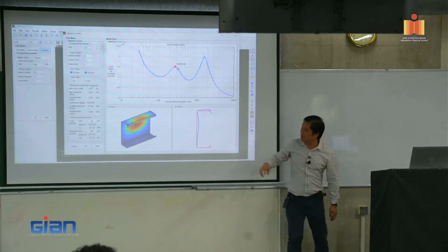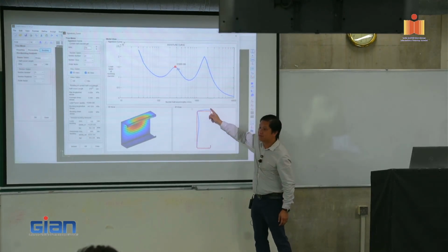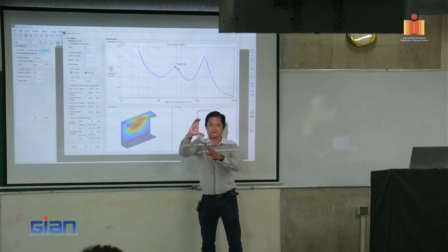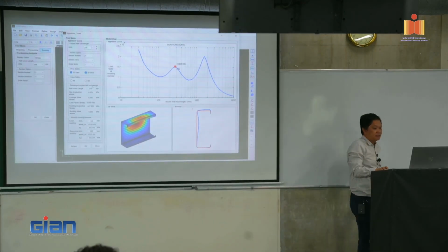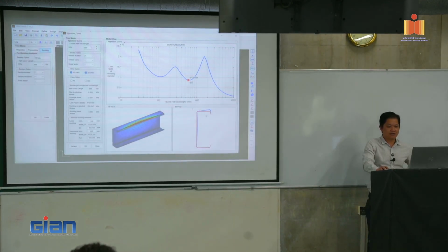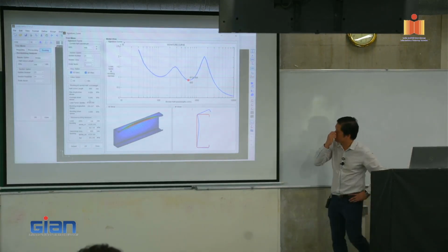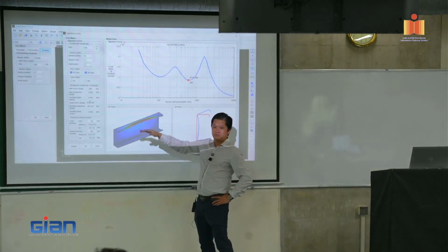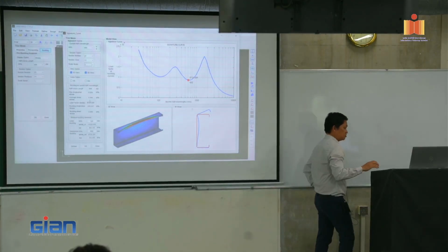And you can see slightly that one moving up in the middle. So it starts to open. So that's distortional buckling, and it's going down. And here, you see that they're picking up the minimum point is 600. Okay? So you can scale it up if you want. You see it clearer. You can zoom it up like 3 times. So exactly, you see the failure mode of distortional buckling.